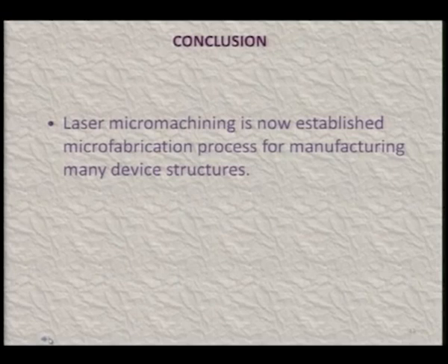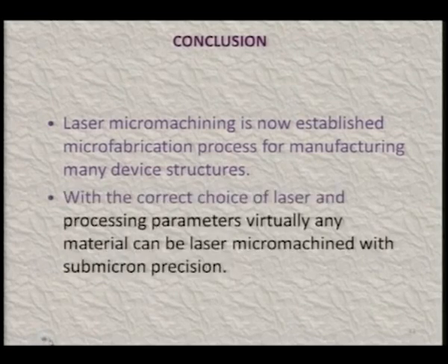Now, in conclusion, I would like to make two conclusions here: that laser micro machining is now established as a micro fabrication process for manufacturing many device structures, some of the examples of which I have shown to you at the end of the applications, and with the correct choice of laser and processing parameters, virtually any material can be laser micro machined with sub-micron precision.